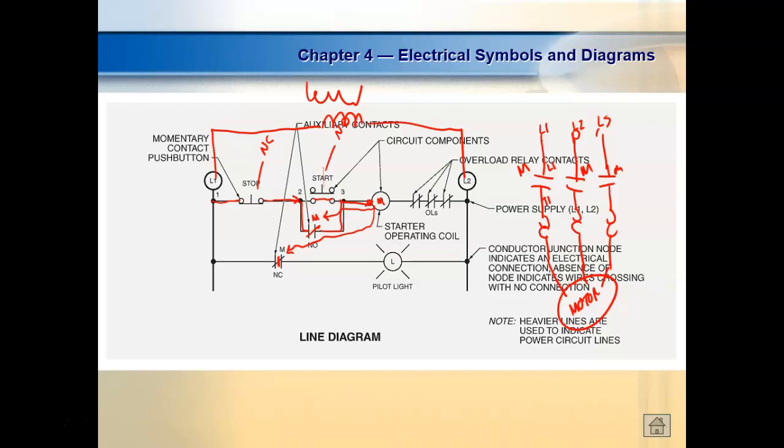So basically most control circuits are made of two circuits. So we have the what? The control circuit that just shows what's controlling things. And then we have the power circuit, which is actually where the power is involved. Now, why we like to do that, it allows us to actually break these up, right? So we'll have one cabinet that's low voltage that everybody has a key to, and then you'll have one cabinet that's high voltage that probably takes 2 or 3 keys to get into. Getting inside the higher voltage cabinet will kill you if you mess up. Getting inside the low voltage cabinet will probably hurt you. Some of them can kill you, but it has a lot less chance of doing that, right?